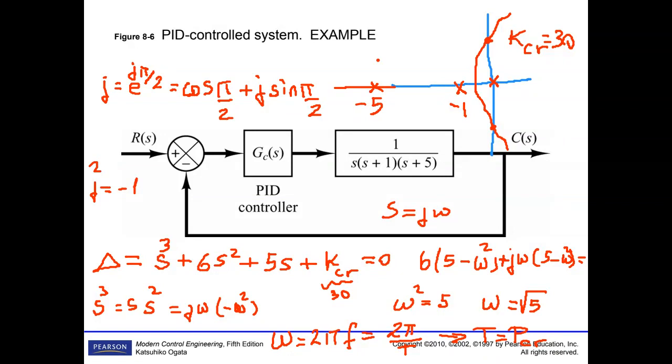When you click on the block, with Control R you can flip it. So this is just gain, you can change your gain. Let's make it 5. And run. We could change the time to 100 or 5 as you need.